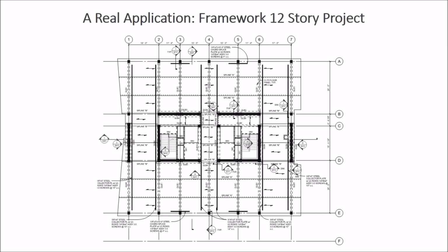This is a typical floor plate of their system where we have 8 rocking walls around the core. These are on the exterior at this end, but then 6 around the core. And then we have cantilevered diaphragms in this direction, going to the north and south on the plan.